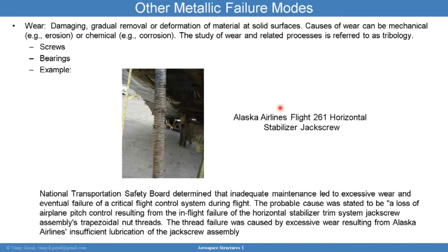And so the probable cause was stated to be a loss of airplane pitch control, which resulted from the in-flight failure of the horizontal stabilizer trim system jack screw assembly's nut threads.